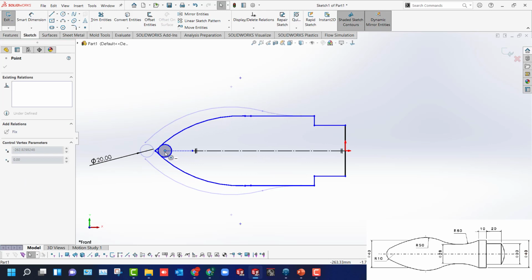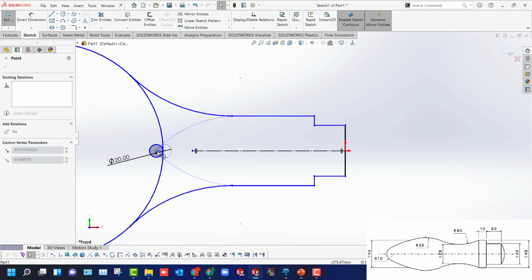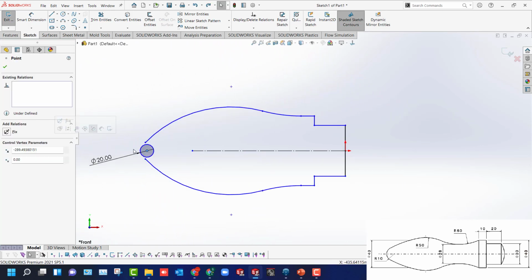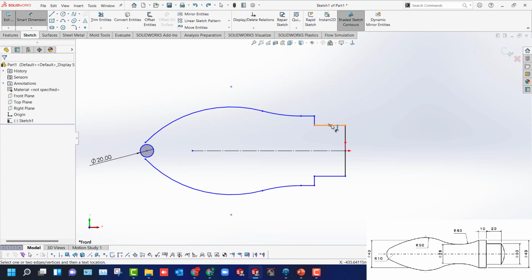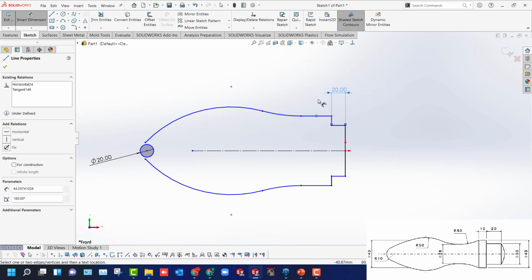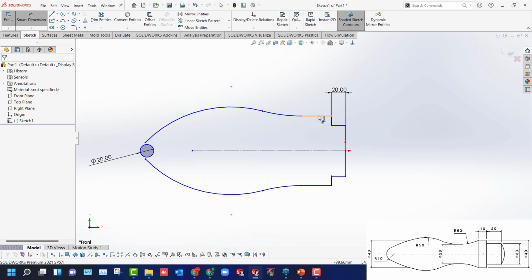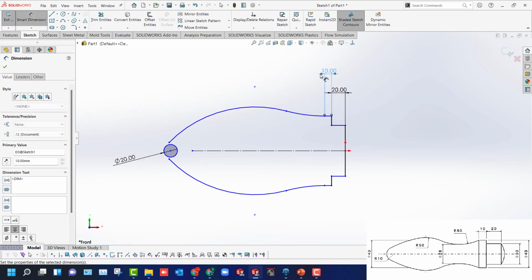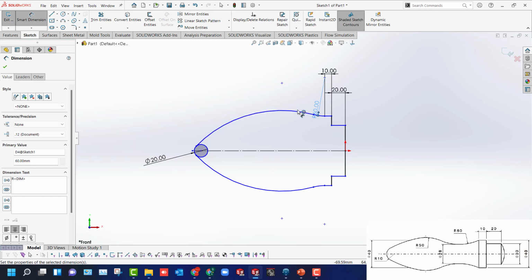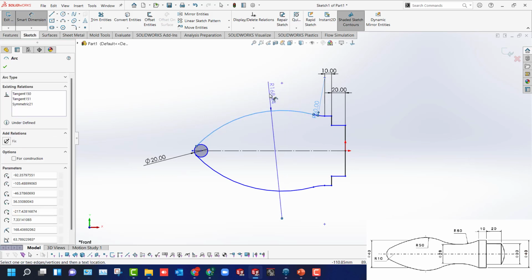Yup, this. If I move it, okay, the complete shape will change. This is a mistake now. Control Z will help you. Yep. Now I'll define the dimensions first because the shape should not change. 20, this complete distance. This is 10, not from the center actually. This total length 10. And then the diameter. This is 60 radius, and this is 50 radius.